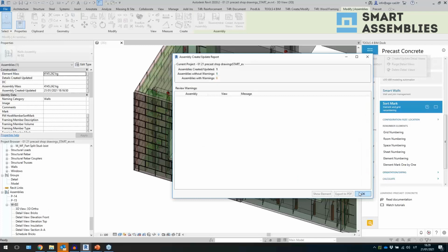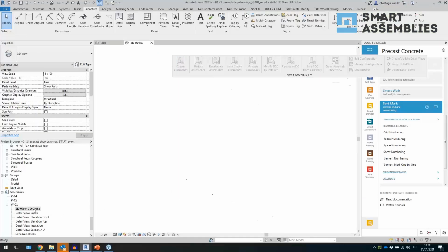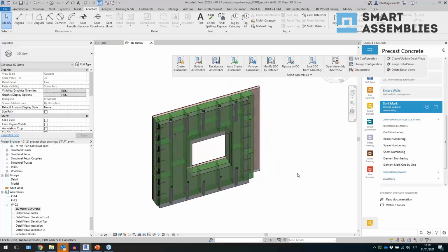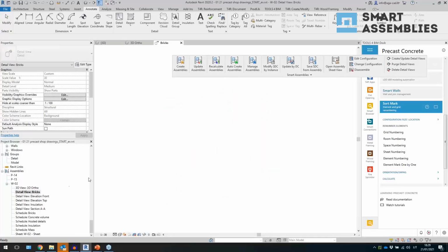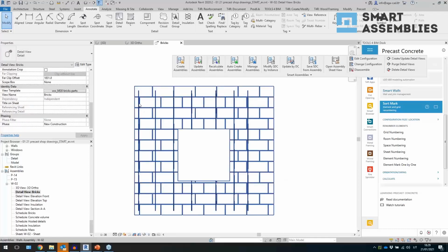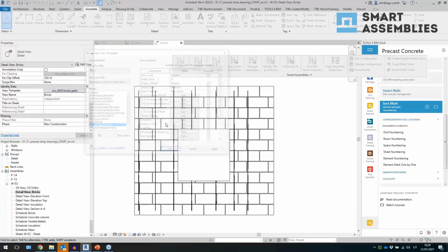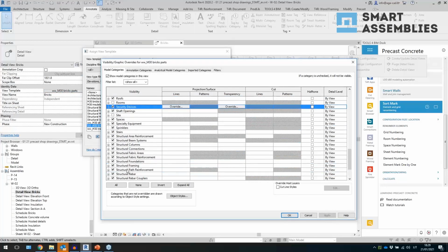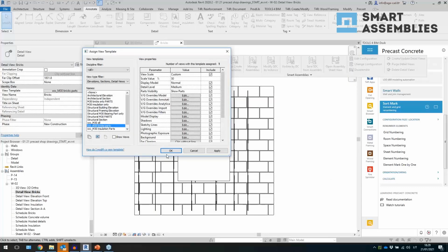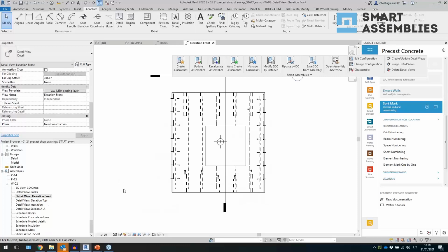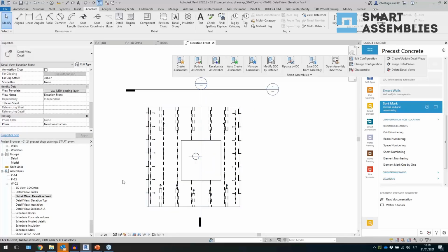So we will have a 3D view now, right? So that's the settings what I had in my 3D view template. Then I have a brick layer. Okay, this one, I see these structural framing elements, so actually I don't want to see them. I can just simply hide these structural framing elements. All right, then I have this front view where is a bearing layer. I have location of sections.